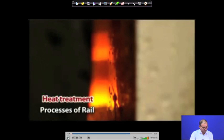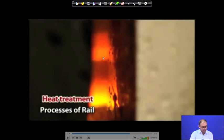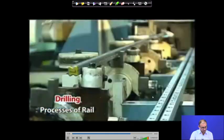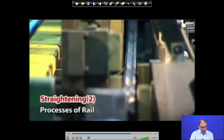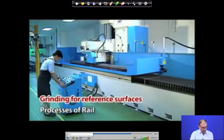So, heat treatment is required because you do not want these parts to deform during operation, be it static deformation or dynamic deformation. So, these are the steps: first straightening, because initially you have to straighten it, and then drilling, because we have to mount many things here. Then straightening process 2; after each and every operation you have to perform the straightening operation again.